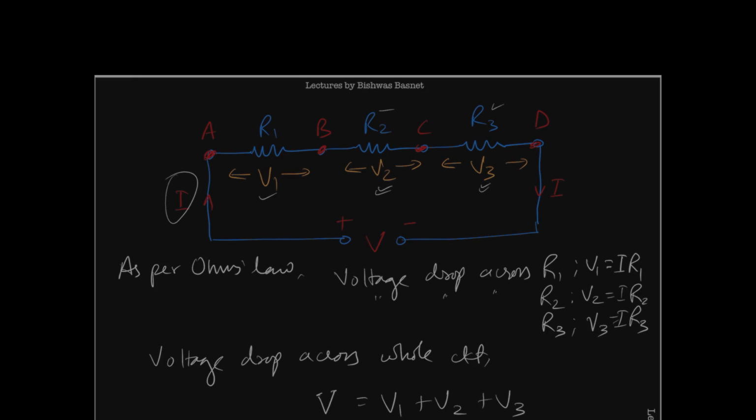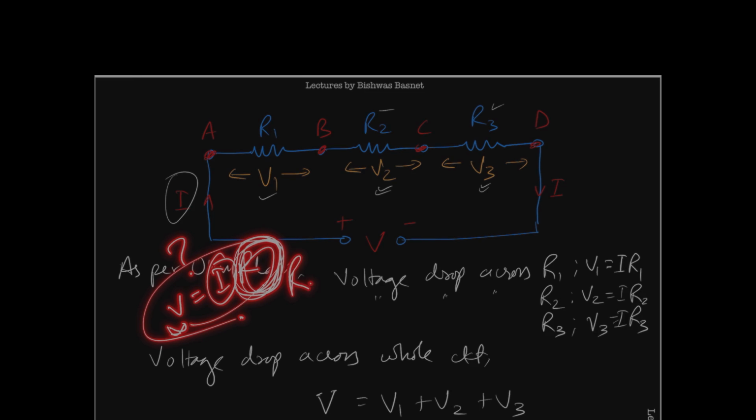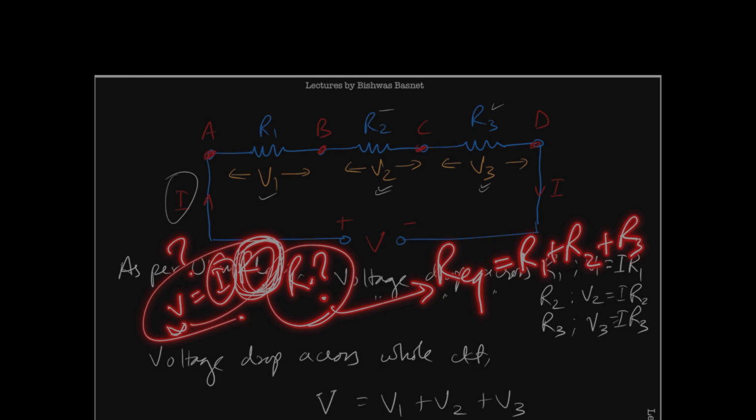So you will certainly remember Ohm's law. It says V equals IR. Okay, I should be able to calculate things from here because you know V. Someone is asking what's I, but this thing is missing here. What's R, right? So what you will do is quickly say, okay, Req for this series circuit, because this is a series circuit, must be R1 plus R2 plus R3. Well, that's known. Now 1 ohm plus 2 ohm plus 3 ohm, right? Now you will find what ohm this is, right? So 3 plus 2, 5, 6 ohms. Great, you know Req now.